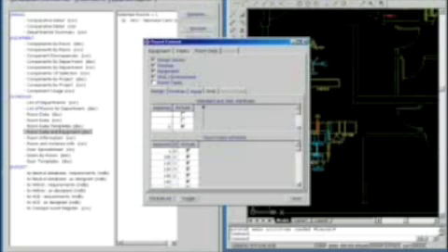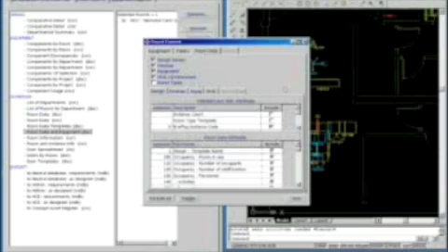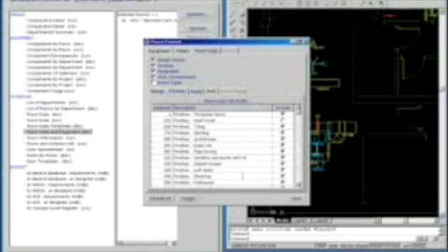In the case of room data, I will select the categories and attributes that I want to hit on the report. For example, in finishes, I may not have any dado rails in my project or any glazed screens. If that is the case, I would not want to report that data. For the purposes of this presentation, I'll select everything that I can.